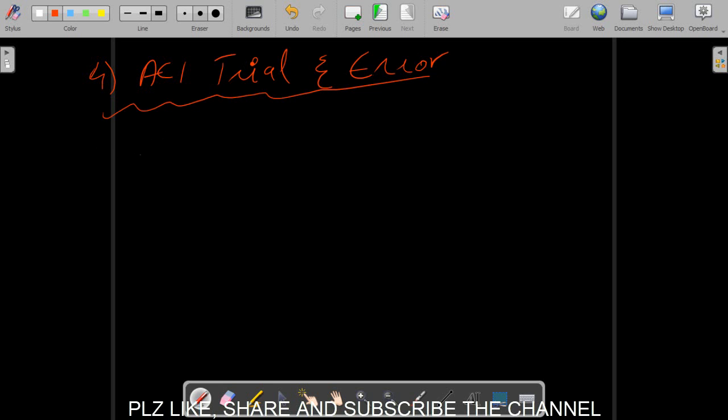Here we will assume the value of a. The a value can be assumed as d/3 to d/4. Most of the time we will assume a equal to 0.2 times the effective depth d, which we already calculated. This is trial 1.